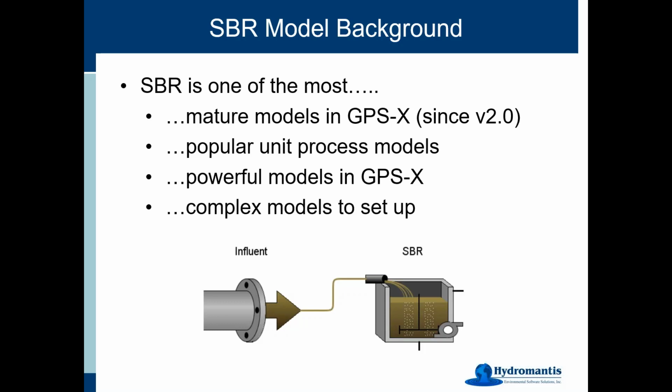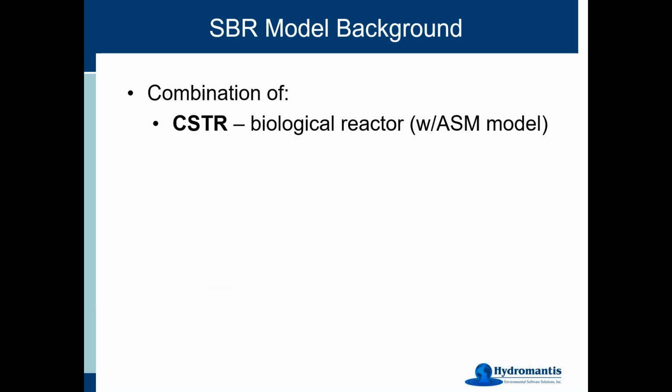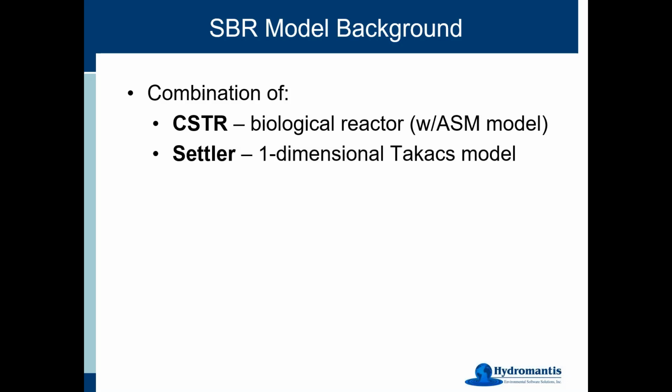It's certainly one of the most powerful models because there's a lot going on there, but it is indeed one of the most complex models to set up. So really, the SBR model is a combination of a completely mixed reactor with all the associated biological reactions that go on in our typical CSTRs, along with a settler.